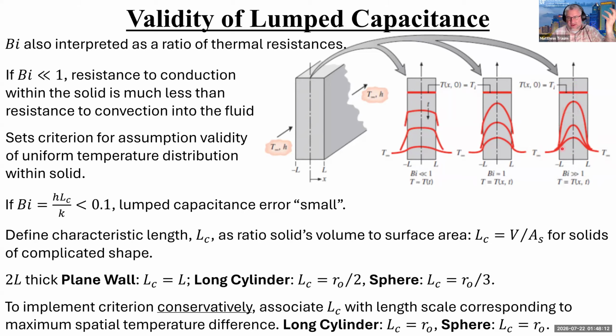So there's a pretty significant resistance to heat transfer across this wall. And that's what's causing this large high temperature in the middle, and then T wall being almost equal to T infinity. Okay, so hopefully you've been able to visualize that as I walk through it.